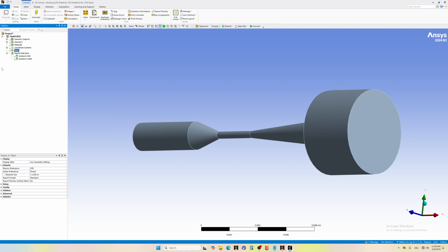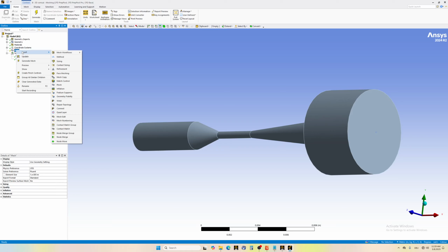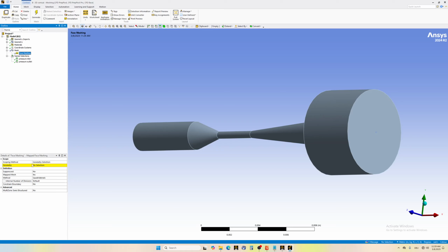So here when we mesh, we will have to use two different meshes, on the surface and in the volume. It's not absolutely necessary on the surface, but it's good to have it because the quality of the meshes is much better. So right click on mesh and face meshing, okay, geometry. Then since it's a surface, you don't have to choose here, it's automatically chosen.